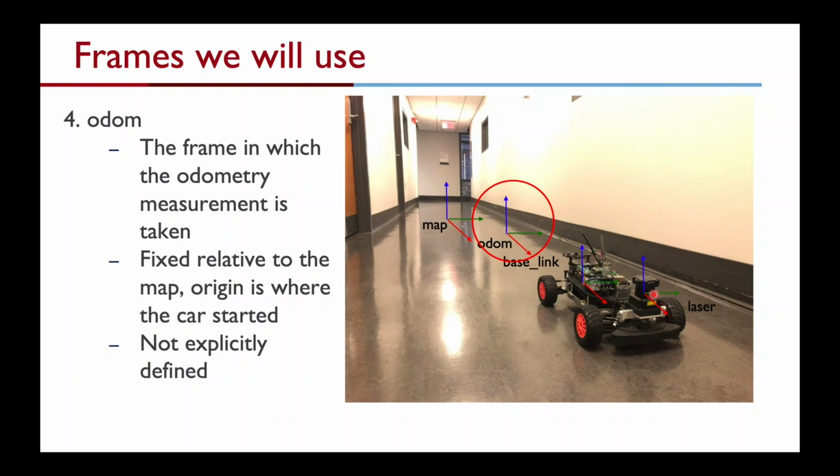Right, so you have your corridor here. I defined the origin of the map to be the center of the corridor, some distance away from the wall, and maybe the car was kept a little bit towards the side of the x-axis to begin with, and so that's where I will initialize my odometry frame. As the name suggests, the odometry frame can give you the transformation between the base link and the initial position as calculated by either dead reckoning, using an IMU, or using the VESC. We have discussed different methods of odometry to estimate the pose of the robot.